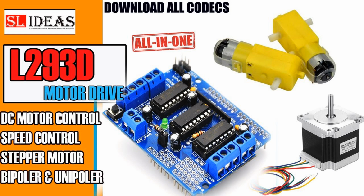1. Basic servo motor drivers, PWM-based. Function: basic servo drivers control the rotation of the motor by generating a PWM, pulse width modulation, signal. This signal determines the position of the servo shaft. Operation: servo motors typically have a control input that requires a PWM signal with a fixed frequency, e.g., 50 Hz. The position of the motor shaft is determined by the duty cycle of the PWM signal.